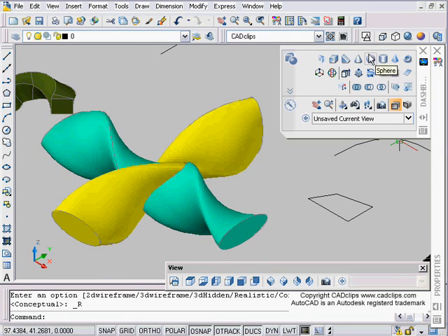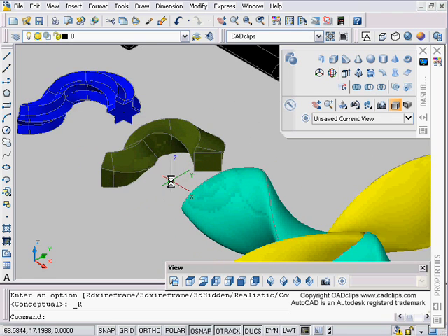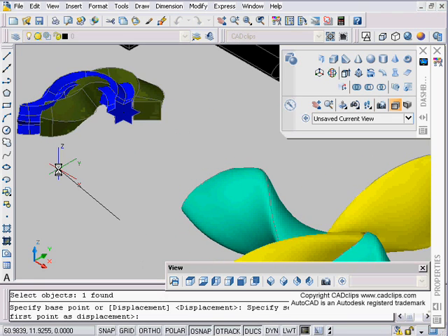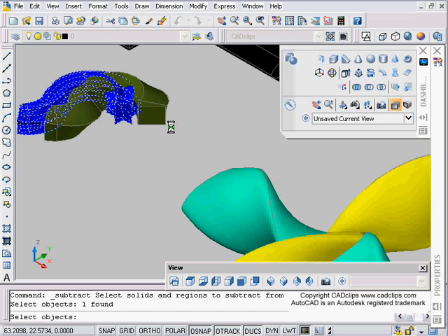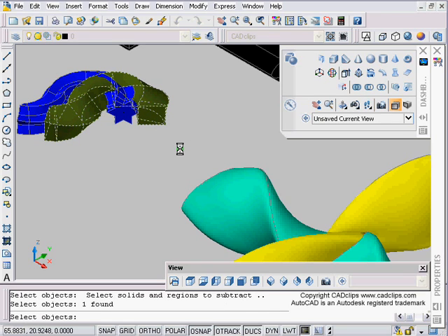Try it out, experiment, get creative, start to use all of these tools we've been talking about. Don't forget about our Boolean operations of intersect, subtract and union, where we can take these objects and start to blend them in with each other, and then maybe do a subtract from this, enter, this, and then it'll actually remove from that.